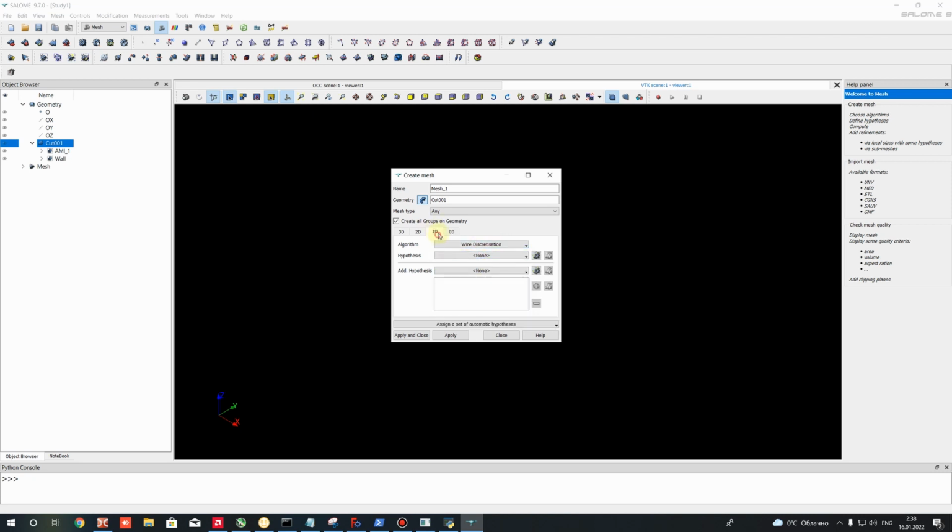So let's use this. Go to the 1D and let's set the adaptive. And here let's set also, for example, the minimum will be 0.001, for example, and maximum 0.02, to be 20 millimeters and 1 millimeter. Click OK, and now we have everything we need for creation of the 3D mesh.